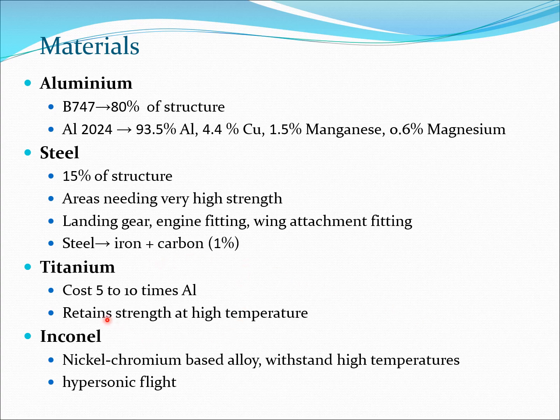Now, titanium is also sometimes used in some parts. Its problem is that it's pretty expensive, so it costs 5 to 10 times the cost of Al or aluminum. But one of the advantages of titanium is that it retains strength at high temperature, and that's something which is beneficial in certain type of vehicles such as hypersonic vehicles or vehicles which are re-entering the Earth's atmosphere.